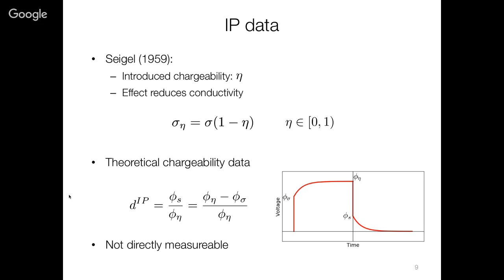And the other reason that we couldn't measure that is why? Exactly, thank you. Yeah, so right here, at the time you're turning off, all kinds of things are happening, right? You've got all kinds of induced currents, and so there'd be extra voltages that are there. So we're not going to be able to see something there. Nevertheless, we are going to be able to start recording, and we could maybe see that curve. And any manifestation of that curve is going to be related to chargeability.